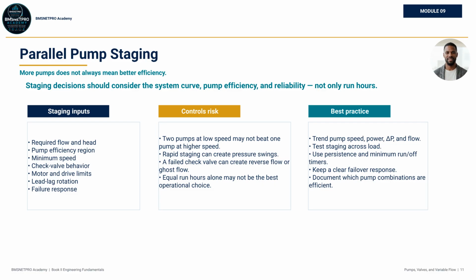Good BAS logic includes lead lag rotation, minimum runtime, failure response, and stable staging. Most importantly, it should be tested across real load conditions. The goal is not just equal run hours, the goal is reliable and efficient operation.